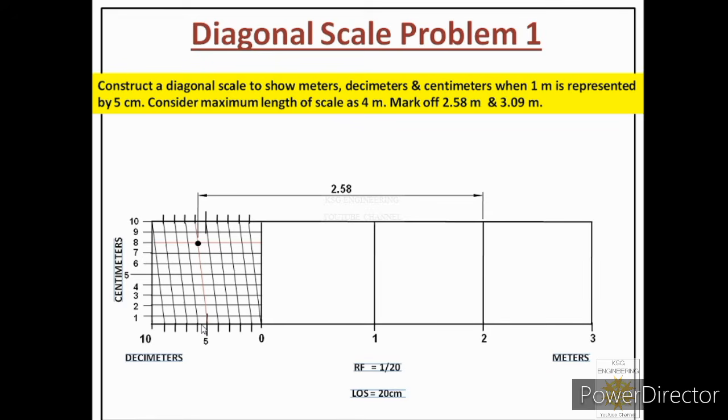So in order to reach that part, we followed the diagonal line, started from 5, and this diagonal line is inclined towards the 6th decimeter, and slowly we are moving towards the 6th decimeter. And if I drop a vertical line from here, it will actually point to the 8th part of this distance. So following the diagonal line, we are slowly moving towards the 8th part. This is known as the diagonal principle. I hope the working of this scale is clear to you.